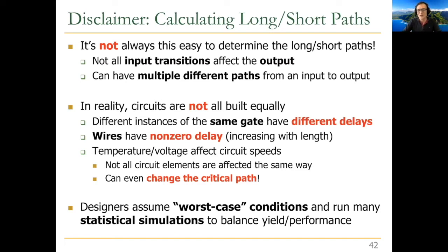I'm not going to go into exactly how these paths are determined, but what I showed you is a good back of the envelope calculation of these paths. And then you can also add some margin, saying that, okay, the rest will take this amount of time based on my measurements, and then you add that margin on top of the delay. For example, that way you can take into account the wire delays that you have in the circuit.